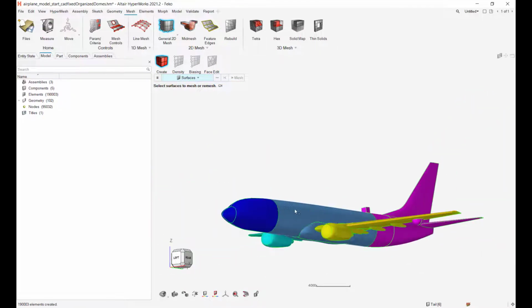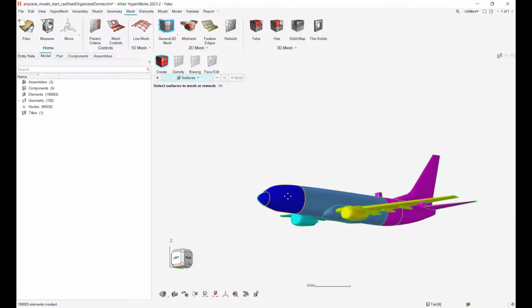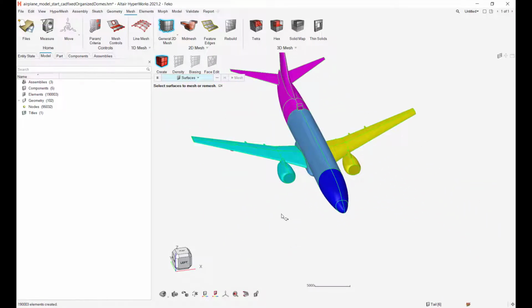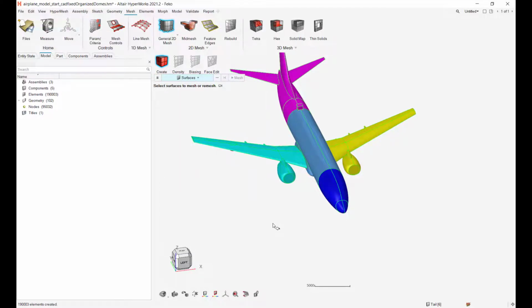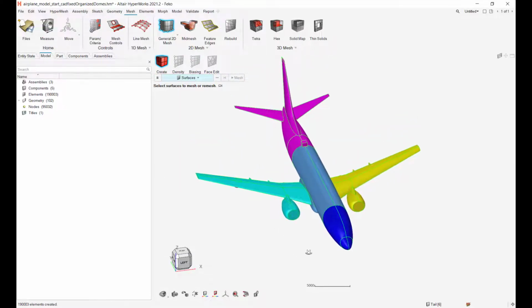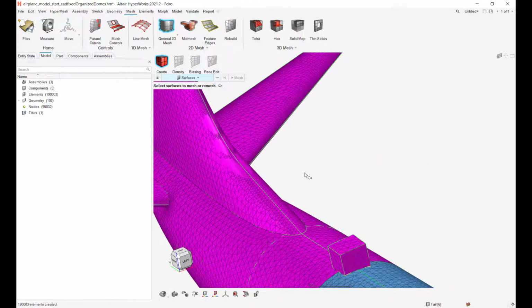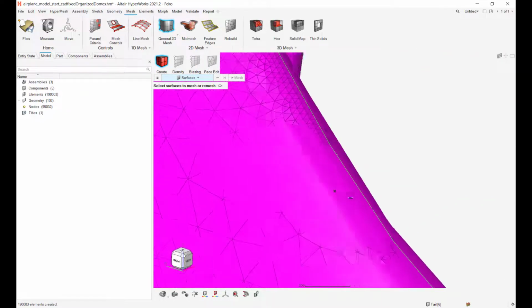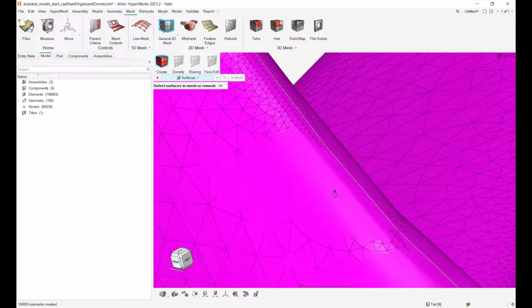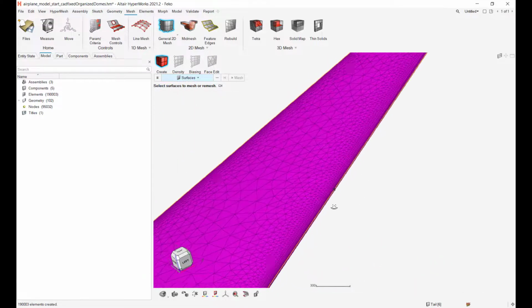Because you could go and mesh this surface by surface. Whew, that would be a job. Okay, so this was the curvature-based refinement. This is where I'm going to stop deleting the mesh and accept my life. I think that this is pretty good, right? So yeah, here's a good place, right? So you can see the surface popping through. It would be much, much worse if we didn't have the curvature-based refinement in here. If we wanted to, we could even go in and stack more elements in there. Okay.